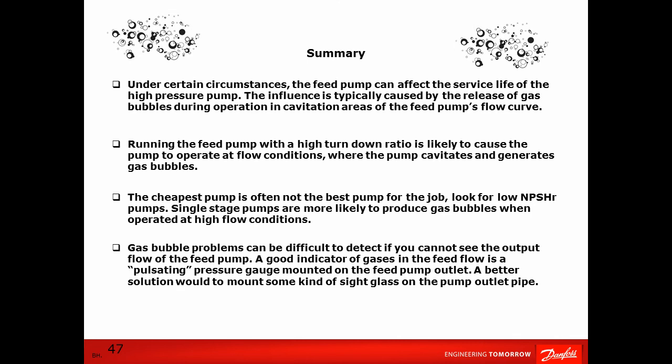It is time for some conclusions. First of all, consider the feed pumps that you are using. Single-stage pumps should not be the first choice, since they can cause cavitation damage if they are operated outside the best performance point. Go for multi-stage feed pumps with low NPSHR values to be on the safe side.